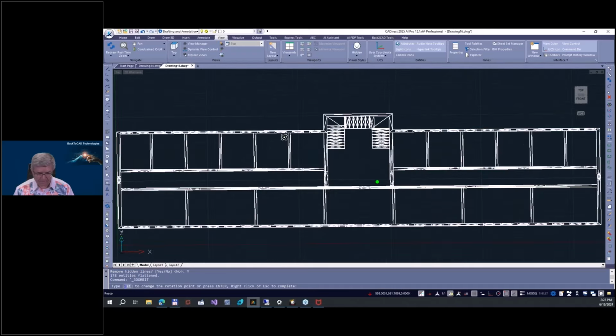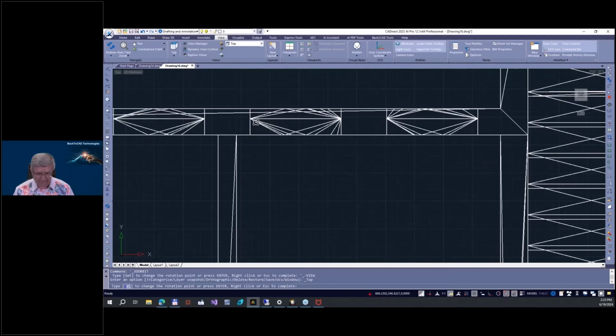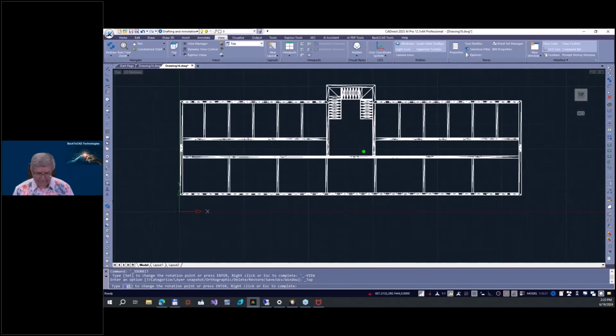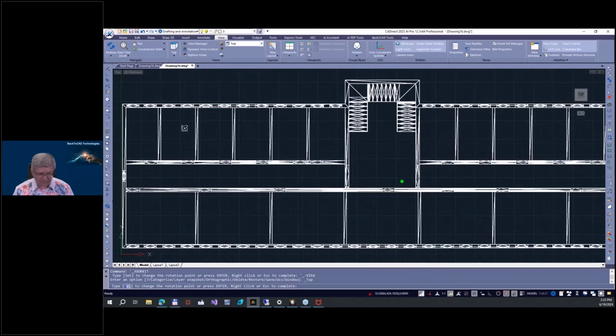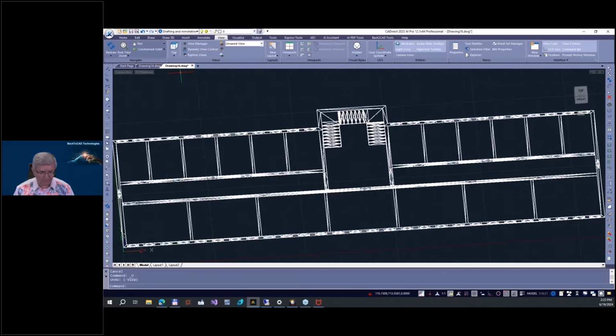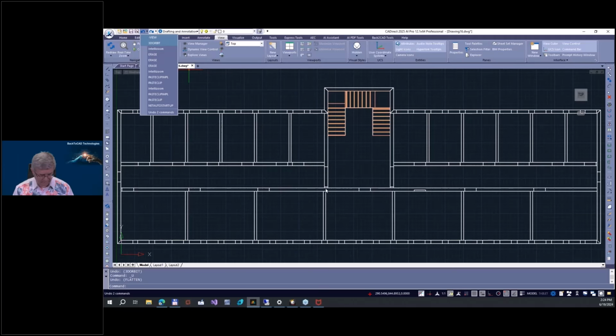You see. But the problem is here that this flatten takes the borders of 3D faces. Like this kind of flatten is not really, you can redraw it now here, but if you need a real drawing, I'll show you another method. Okay, let me go here on undo. This flatten is not really a smart method. So I will show you some better method.